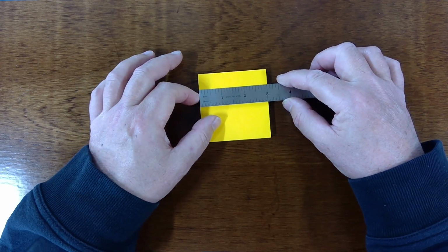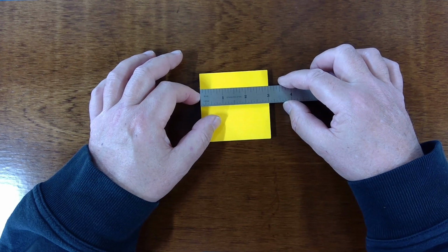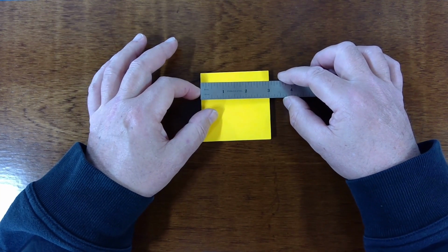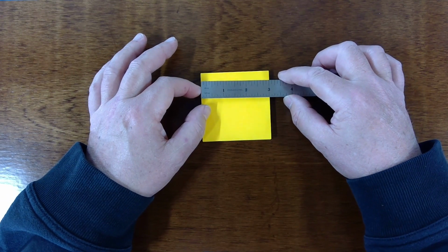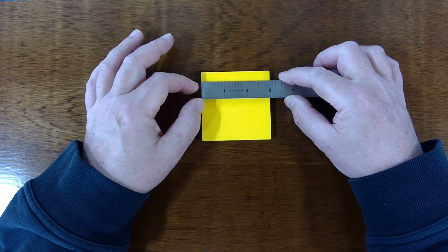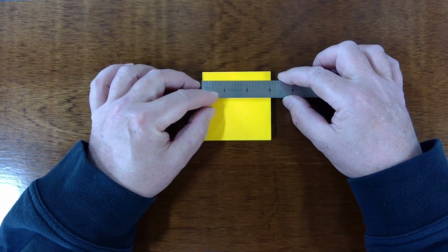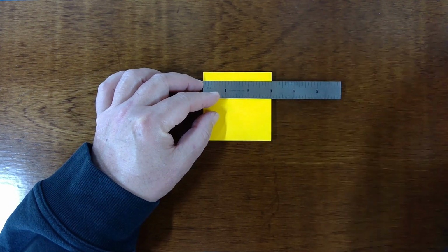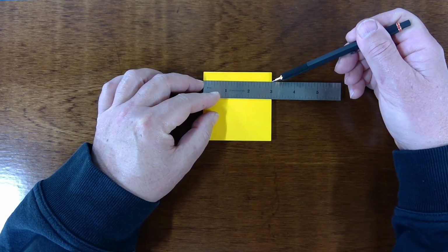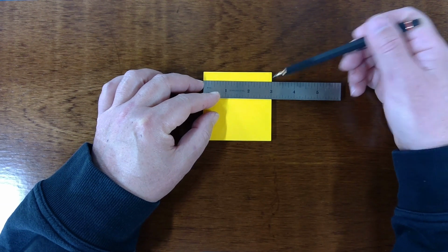But let's say you were going to draw this in the CAD system. You would make it exactly 3 inches, 3.000, exactly 3 inches. But if you were manufacturing it, there's no way to make it exactly 3 inches. You just can't do it. So what you do is you specify a tolerance. For example, you could say, make this thing 3 inches, plus a certain amount is okay, and minus a certain amount is okay.